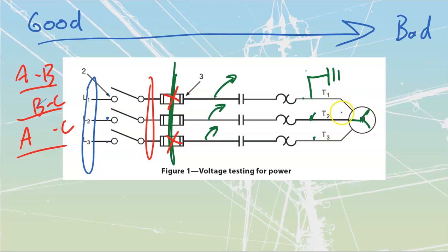What I would then need to do is look at the magnitude. If you've got a good quality ohm meter, it should be able to go into the hundredths of ohms. Once again, power off because you're working with an ohm meter, take your measurement. If I measure from this line over here to ground and I measure 2.2 ohms, and then I measure from this line to the same ground and I measure 2.1 ohms, I would know that this one would have to be just a little bit closer for some reason. And if I measure on this one and I'm measuring 1.8 ohms to ground, it is going to be the faulted line.